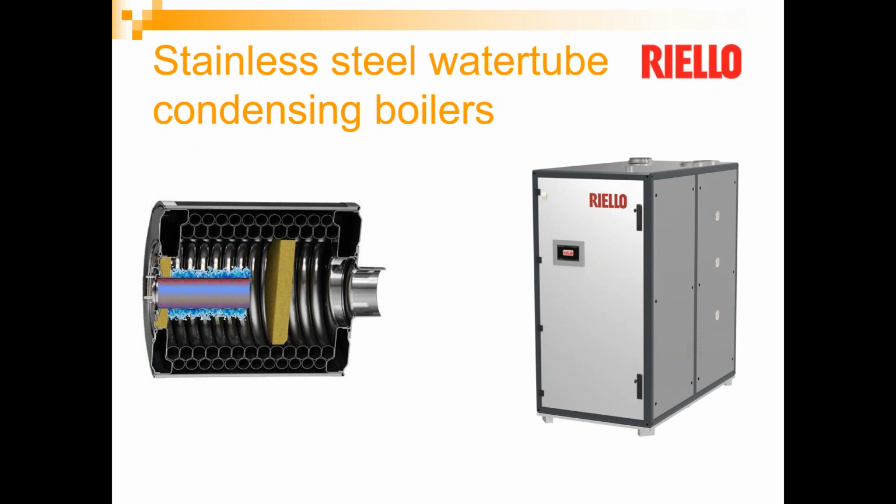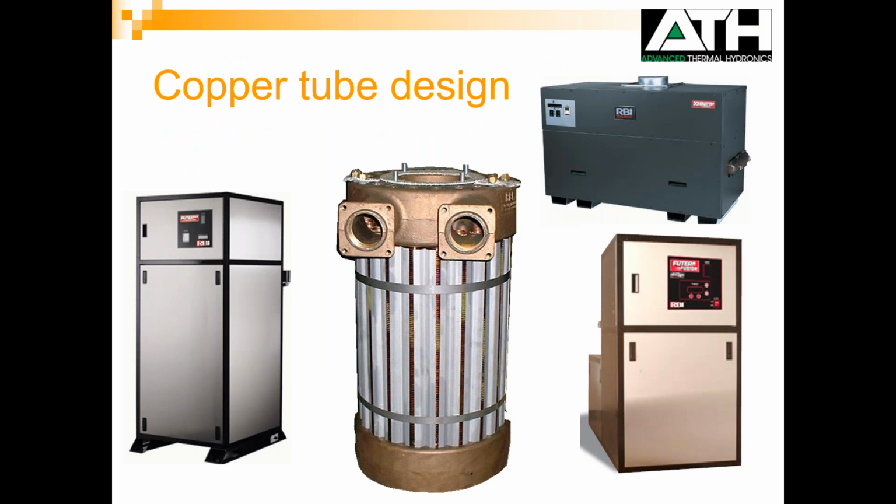This boiler is a modular type of boiler where a 2 million BTU unit actually has 4 burners and 4 500,000 BTU per hour modules, giving a number of advantages from redundancy to repairability in the field. Other types of boilers are copper tube boilers like these from Advanced Thermal Hydronics, part of the Mestek family of companies that we sell.